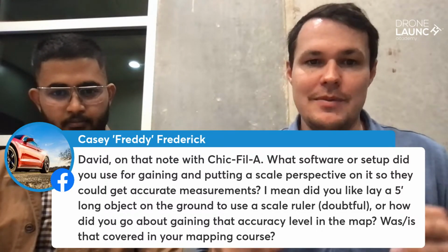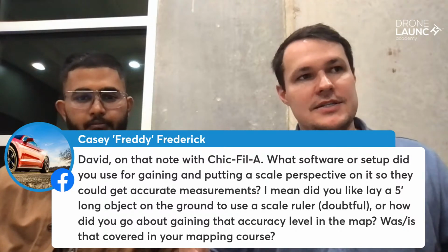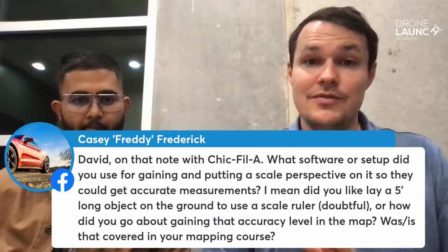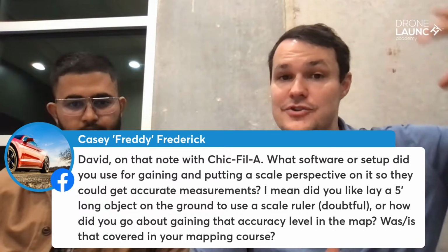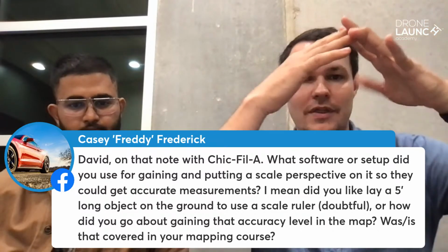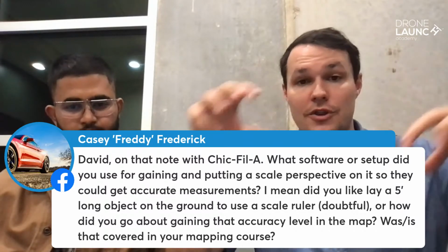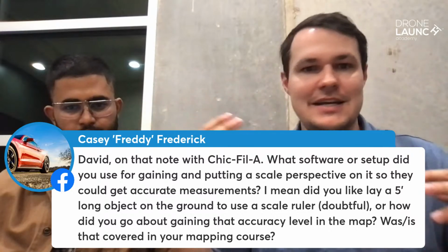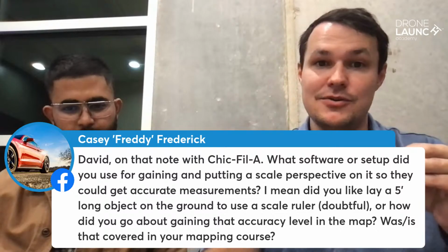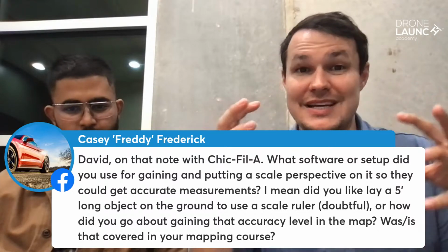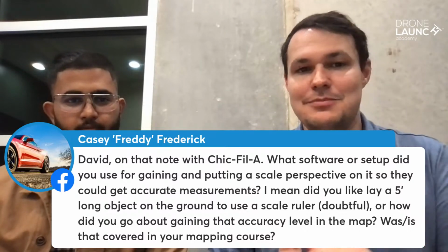The software will automatically know the accuracy and the distance, because of some formulas that happen in the software. We covered this all in the course, but it's called ground sampling distance. So it knows how high the drone is above the ground, and it does calculations to know what the field of view of the camera is, and it can do the math to figure out what the distance is on the ground, and it knows the GPS location of all the pictures. So it uses all that data to come up with the measurements, and what it actually does is convert measurements into pixels, and what you're doing is measuring pixel to pixel inside of your map, and how accurate it can be depends on your ground sampling distance.